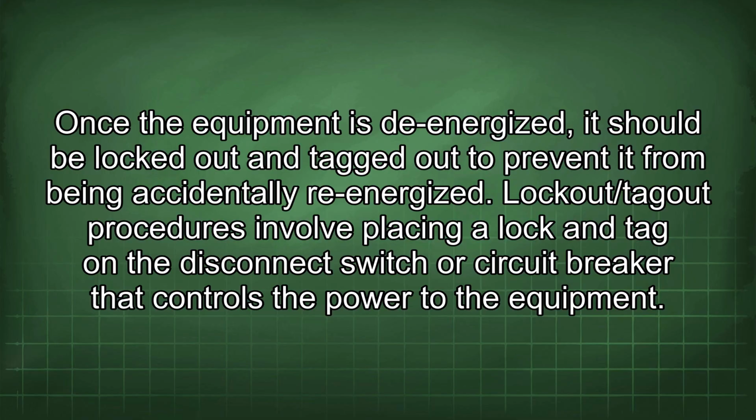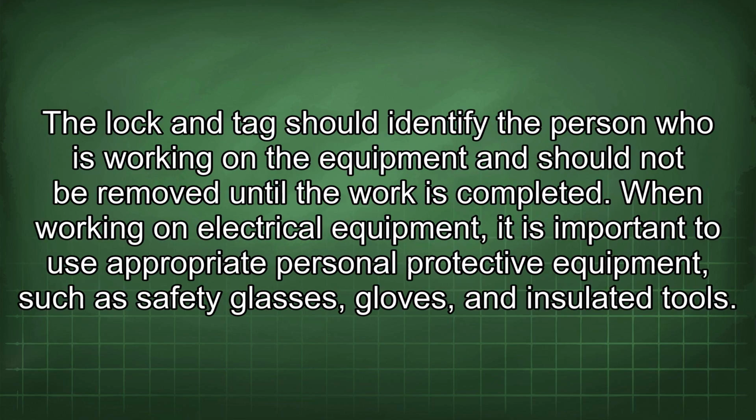Lockout/tagout procedures involve placing a lock and tag on the disconnect switch or circuit breaker that controls the power to the equipment. The lock and tag should identify the person who is working on the equipment and should not be removed until the work is completed.